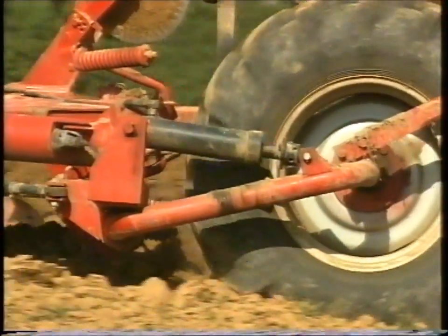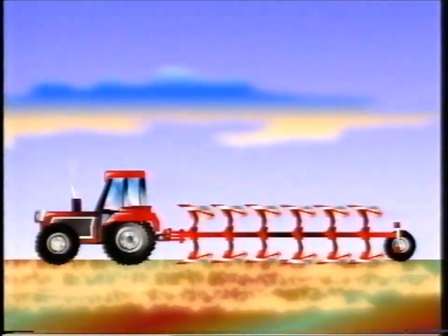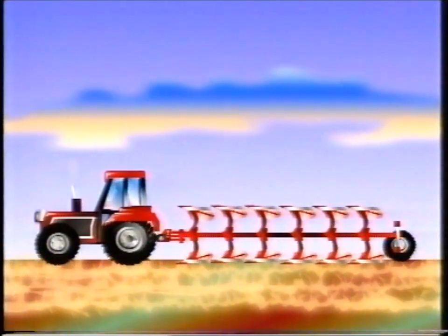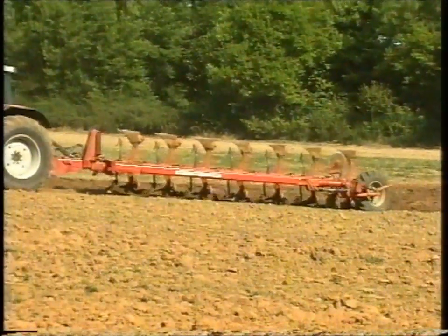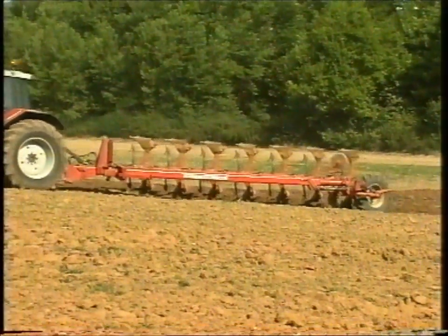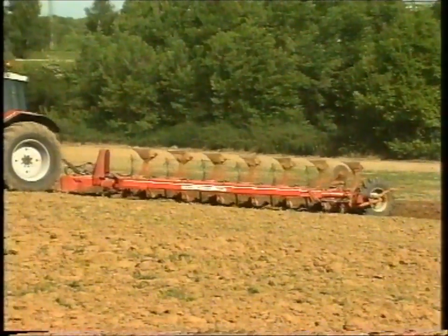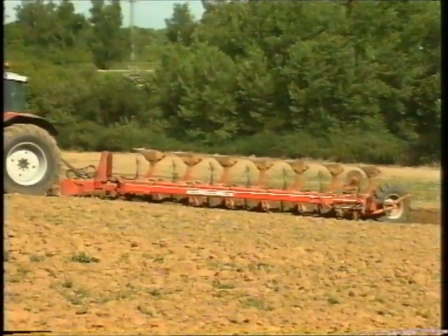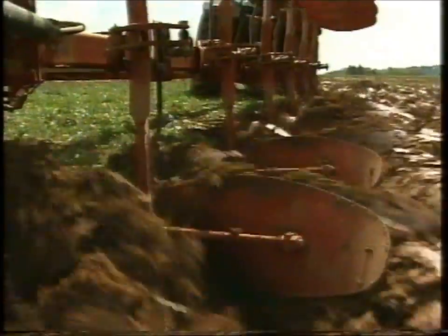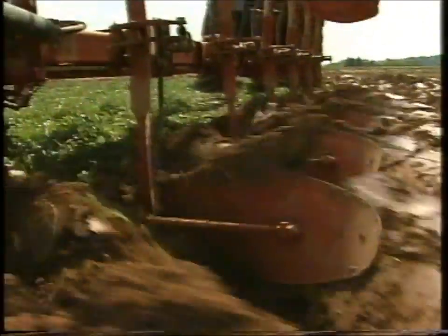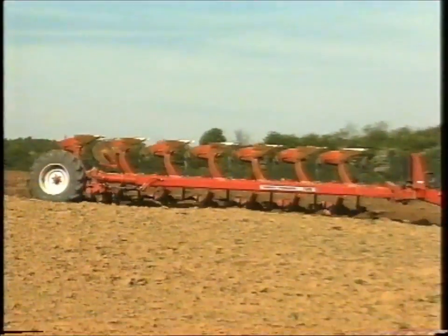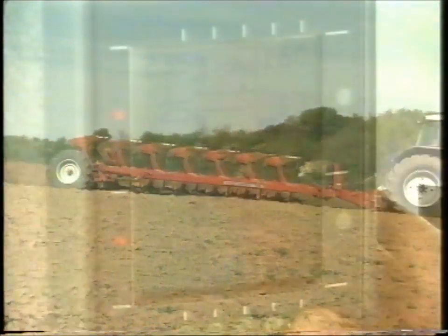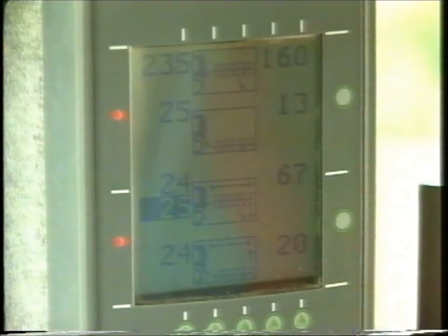With the Datatronic II control interface and ELC, all these problems are overcome. Firstly, dual control allows the ELC to control the position of either the rear or mid-mounted depth wheel, so that it moves in unison with the lower links. Any change in draft force will now result in the plough moving constantly in parallel to the ground, maintaining a far more even depth of work, and also improving weight transfer.